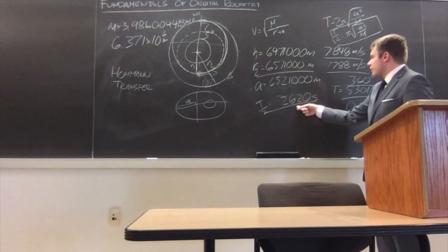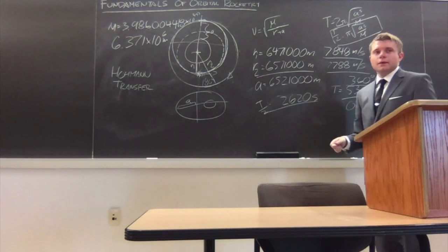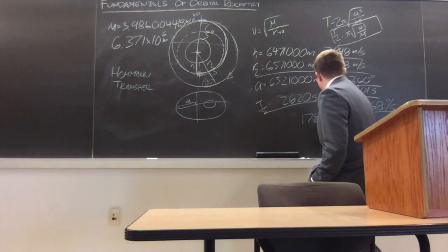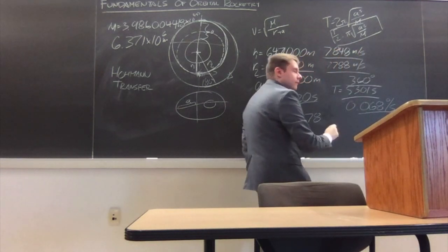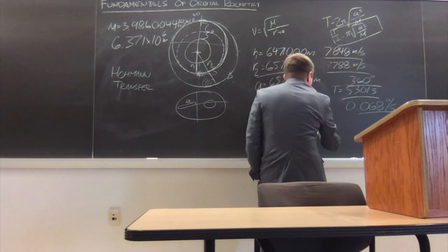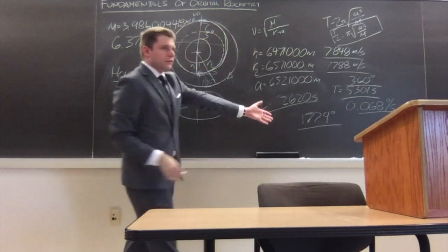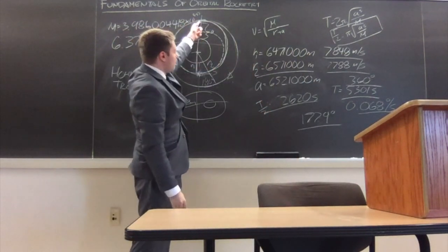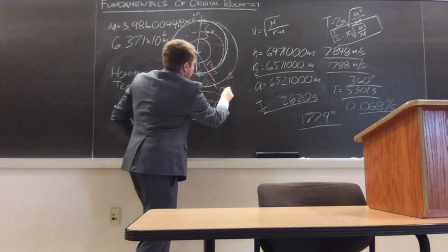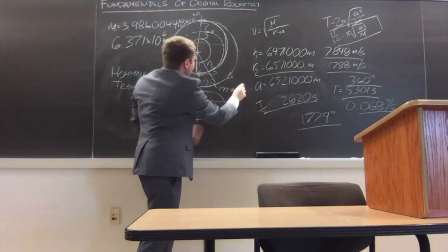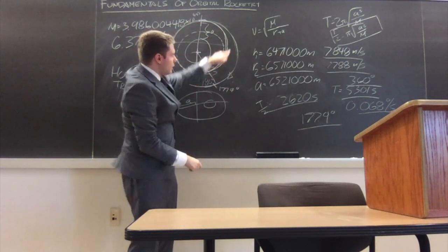So then how many degrees does it cross through in the amount of time that we have available in that half orbit? 178 degrees. Oh, it's 177.9. Now let's use that. So that means that, in conclusion, our target vehicle has to be 177.9 degrees away from the point that we meet before we start our burn and enter the Hohmann transfer.